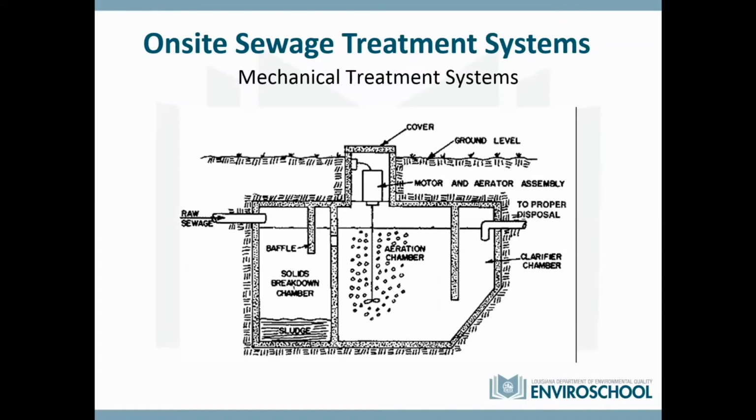So they do what they do, and eventually some of that water starts flowing up to the right side into that clarifier. And the lighter water, the more clear water, actually discharges through the discharge pipe, while the solids, after the water slows down, start going back down that angled area and get sucked back into that aerated portion for reactivation, basically, to be broken down further.